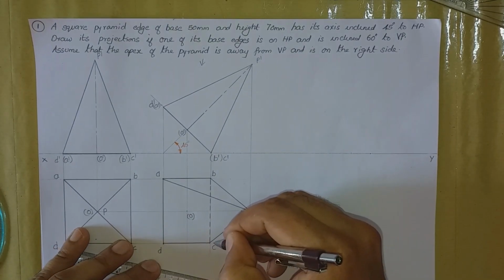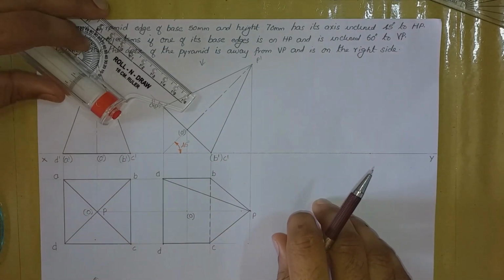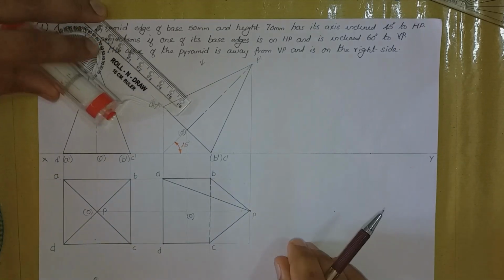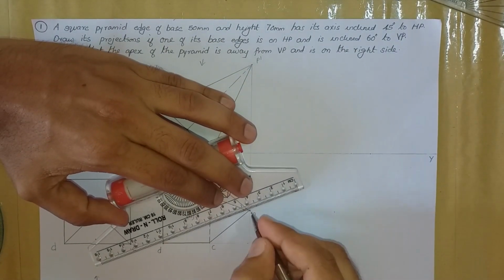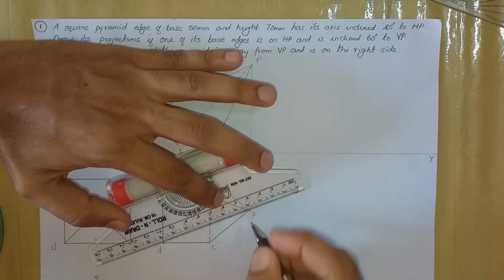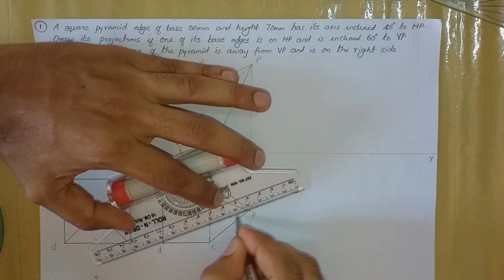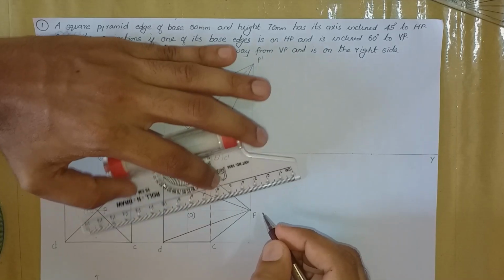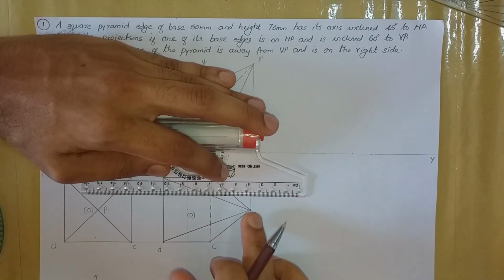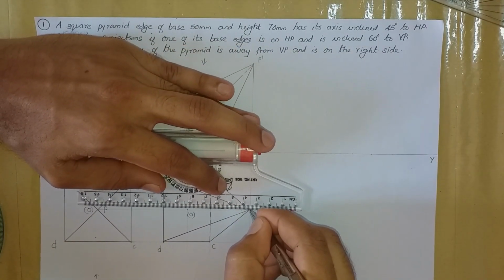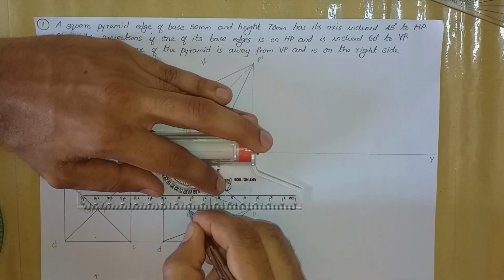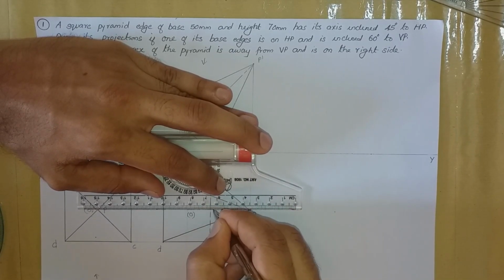PC is also drawn here. Now let us think about the next slanting edge, which is PD. So when you are connecting P and D, it is also crossing a confirmed hidden line. So definitely it will be visible. Now the last step is drawing the axis. So connecting P and D, we shall draw a chain line.